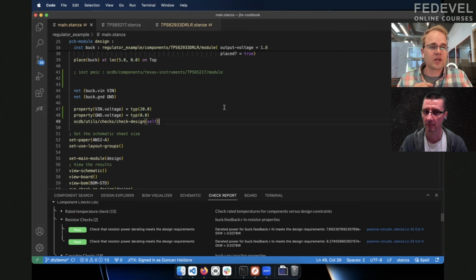And the people on your team don't either, because like I mentioned, you can write libraries that are reusable. You can put checks in those libraries. So if you write your DDR library, for example, you can have a little verification report that runs anytime someone uses that code, so when they include it in the design, you see whether it has been attached correctly. For a crystal resonator, there's a 100-page application note from STMicro about how you get your critical gain and all of these different properties to get a resonator to actually start resonating. But you can just automate it, right? So it just becomes a check: check the resonator.